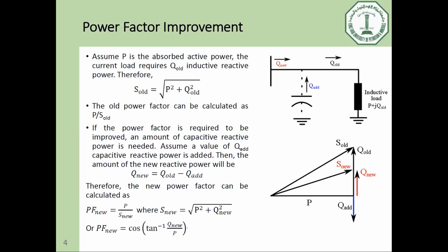In the majority case, we have inductive loads, and we need to compensate the power factor by adding reactive power from capacitive sources. Capacitive sources in our life, like what? Like a capacitor, a static capacitor. Like something else we'll describe, inshallah, in the synchronous machine, which is a synchronous motor in